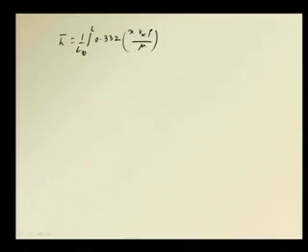So, what we will have? h bar is equal to 1 by L, integral 0 to L, of 0.332, and the Reynolds number is x into V infinity rho by mu, whole to the power half, into Prandtl to the power 1/3, and then hx is equal to this, and we have K by x into dx.